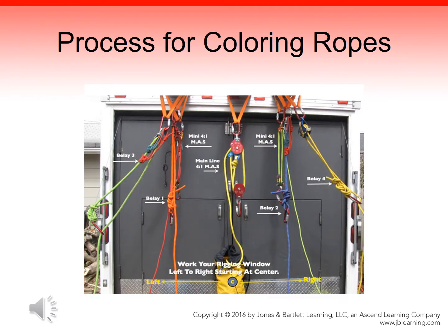The process for coloring ropes. There are two different processes for dyeing rope. The first one is solution dyeing. This occurs during the manufacture of the yarn. It typically weakens the rope greater than surface applied dyeing. Surface applied dyeing is when the color is added after the yarn has been manufactured. It does weaken the rope less due to the dye only being applied to the mantle of the rope.